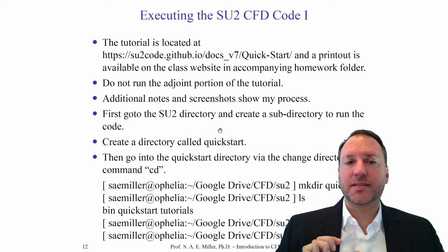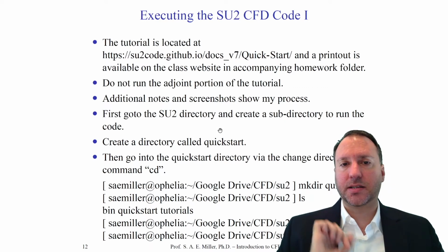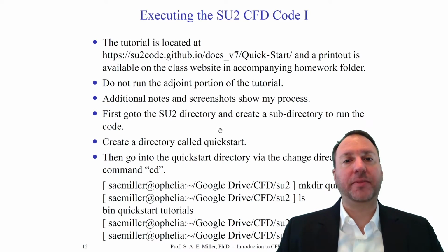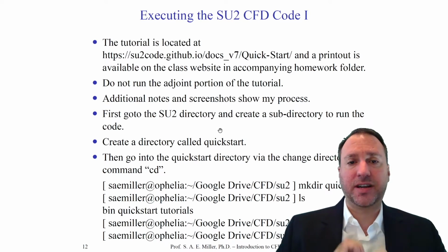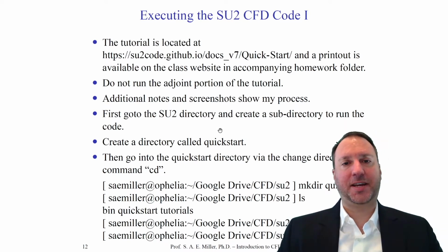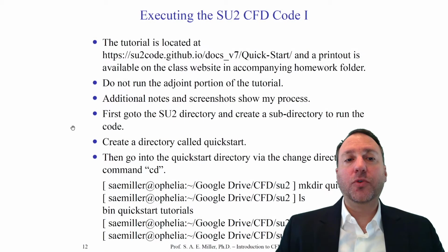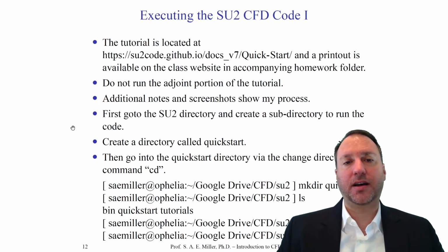This is why for every simulation, every unique case, create one directory and put your files in that directory and run it from that directory. This way it's guaranteed that they're never mixed up. Don't make this mistake. It'll just create a major headache later. We'll call our directory under SU2 Quick Start. I'll show you these commands on, of course, OS X. You can run the similar commands on Windows command line or simply use the Finder or Explorer to do them yourself.